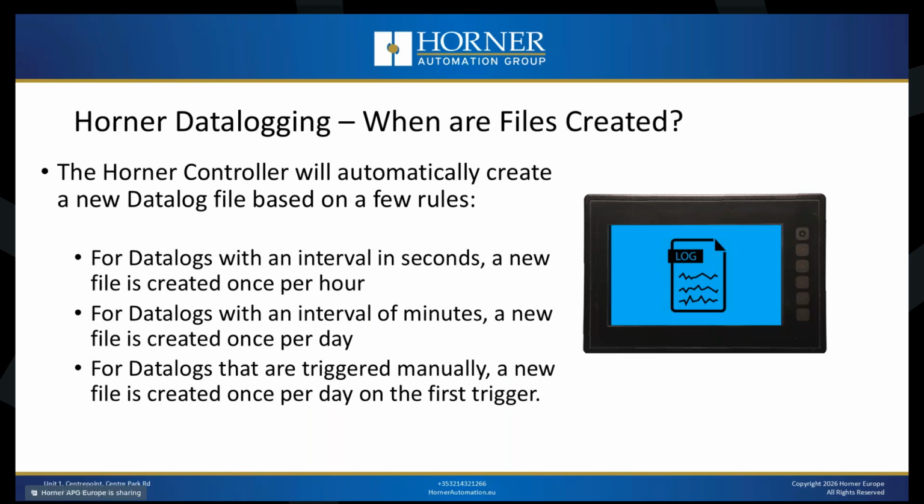When are files created? This depends on how you decide to set up your data logging. For data logs with an interval in seconds, a new file is created once per hour. For data logs with an interval in minutes, a new file is created once per day. For data logs triggered manually, a new file is created once per day on the first trigger.